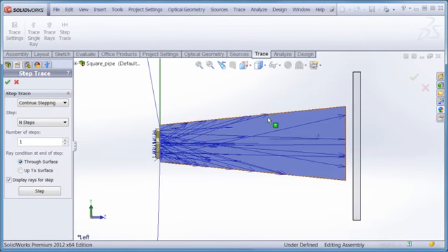Most of the rays will hit along the side where they would totally internally reflect back into the pipe, although those rays exiting the source at a very narrow angle will actually travel right through the pipe without hitting the sides, and then just become incident on the output face. So in those instances where you'd like to see what happens to the light as it propagates through a subset of the geometry in the system, the step trace option is the perfect tool for that type of analysis.